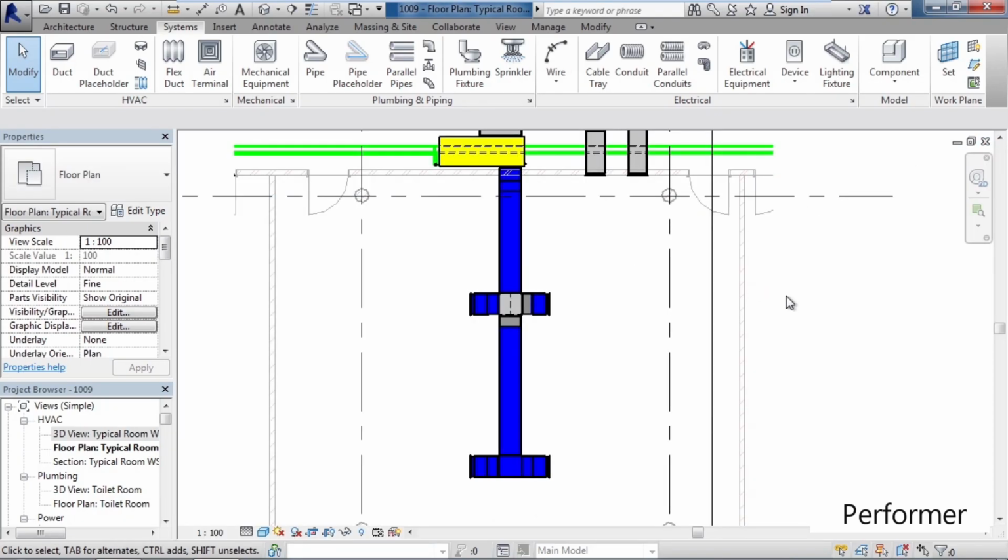So as a review, in this lesson, we looked at an automated way of creating duct layouts. First off, we talked about what needs to be set or drawn. In this case, the supply unit, valve box, or an AC unit. In this example here is the yellow box or the yellow square we see at the very top. We also needed to define the end result, or the diffusers, and I had 4 in this example.